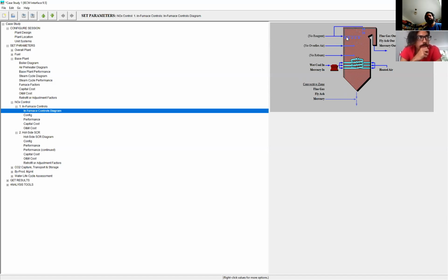What that recycling prevents is the temperature rising too high. The temperature is maintained below, let's say, 2000 Celsius, so you're not going to produce any NOxes. The only problem is that if you don't have a very high temperature, of course, you're not going to be able to produce steam with enough energy. So you tune up the control so you can have the highest temperature you can, but with the lowest NOxes.